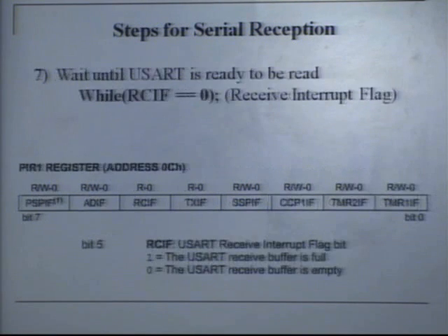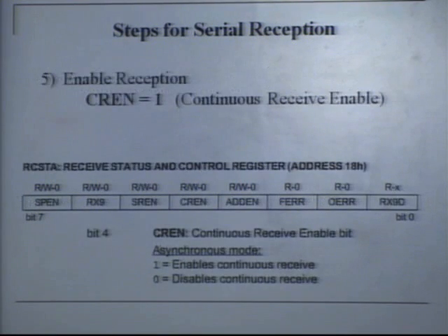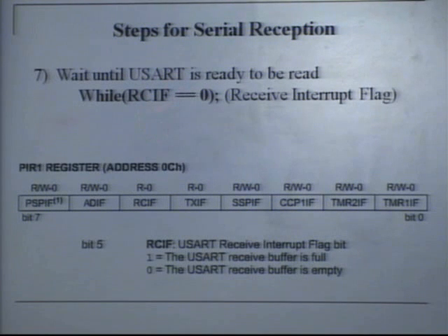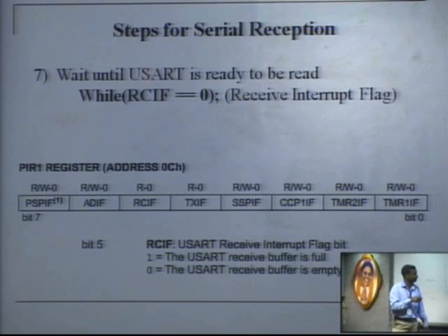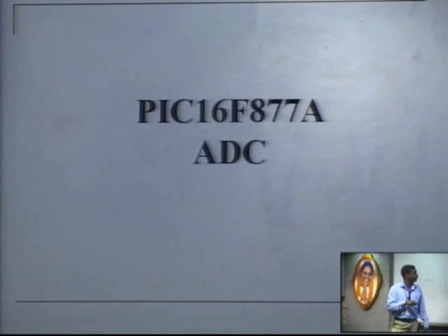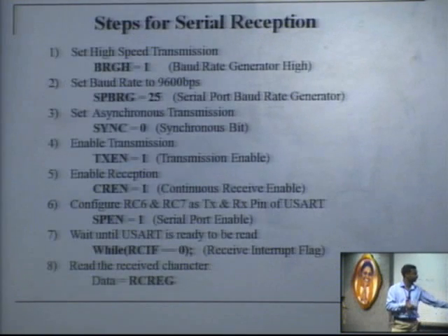Then next step, instead of TXIF, you are checking for RCIF. That is the receive interrupt flag. So after receiving, before taking the character, your character will be present in which register? RCREG. This is the register which is holding the character which has been received.